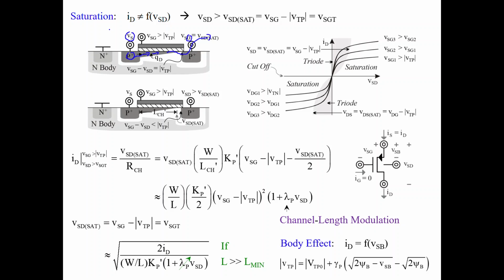And current, since it flows in the direction of holes, is flowing into the source and out of the drain. So this is what we see here. Current is flowing into the source. We use an arrow on the side that is the source, the one that is providing all the charge carriers, and we point it in the direction of current flow, so it flows into the channel.